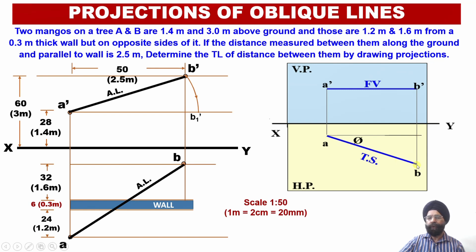in the top view. So from B1 dash, we need to drop a vertical projector up to the locus line corresponding to the point B over here. So this is the horizontal locus line corresponding to the point B. So through B1 dash, we have drawn a vertical projector onto the horizontal locus line corresponding to the point B. So this intersection of these two construction lines is going to provide us with the point B1.